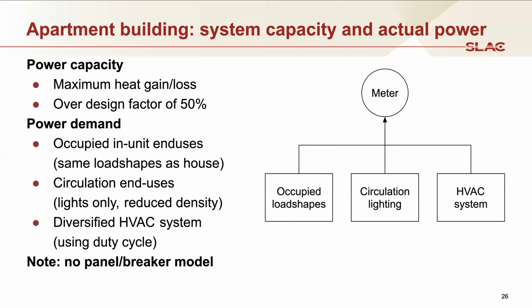We have a question here. Does the thermal model assume that a single R or single U value for the thermal envelope can be adjusted based on other factors? Yes, in both models, the window wall ratio is incorporated in calculating the envelope U value. And doors are also included, and roof and ground interfaces are also included in those calculations. And you can set each of those individually, and then when the house is initialized, the U values are calculated based on what you set those values to.